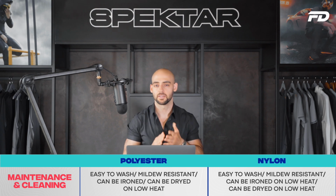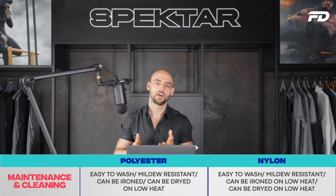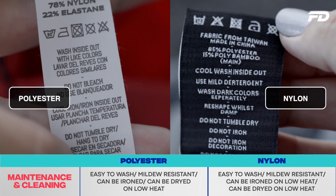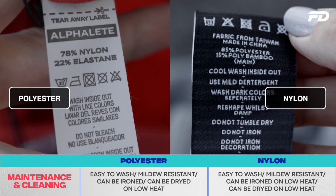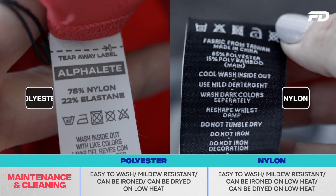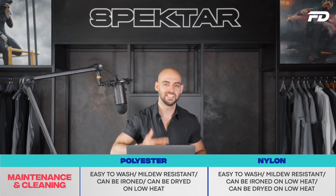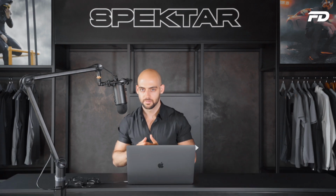Nylon is a little bit of a tricky one. Yes, it can be ironed, but it can be ironed on low heat, and you typically need to have another layer of fabric over it, so it's a little bit more laborsome to iron than something like polyester. And on the flip side, polyester can actually be dry cleaned versus nylon, which cannot be dry cleaned. So that is definitely something to bear in mind. In general, polyester is going to be slightly easier to clean and to maintain over time.